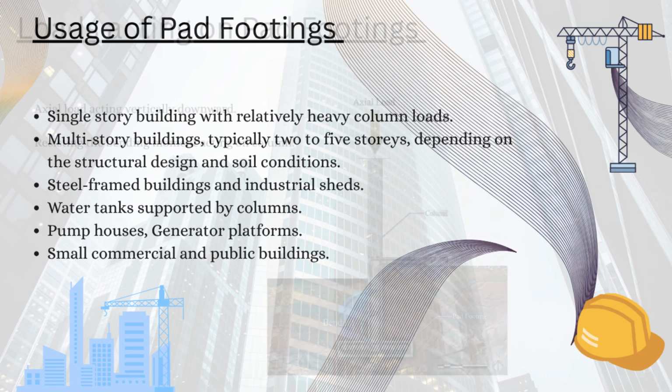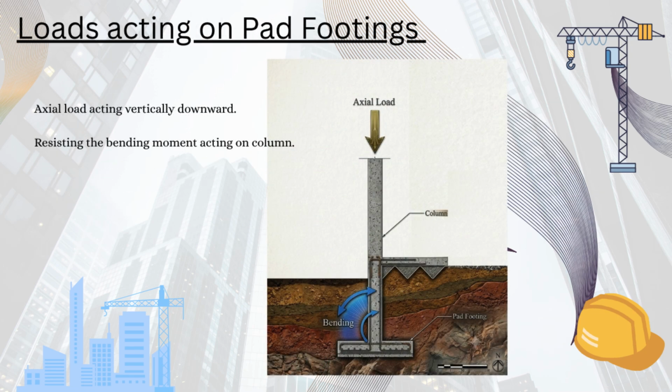The main purpose of a pad footing is to safely transfer the load from an individual column to the soil while maintaining the stability of the structure. It also helps resist bending moments acting on the column and prevents excessive settlement of the building.